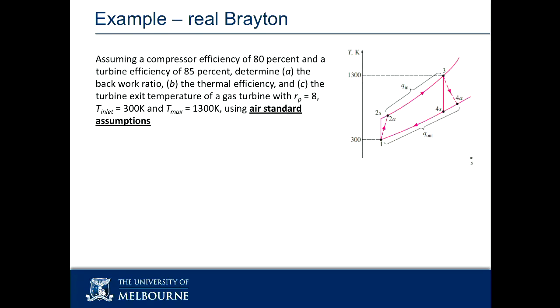What I've drawn up there, let's take our time to look at the graph. We said that we would have an ideal cycle, and our ideal cycles would have the best possible process for any step, which implies that the real cycle has a difference to that. When I introduced compressors and turbines and entropy, I made the point that if I have losses, my compressor and my turbine won't go straight up and down on the TS graph. They will increase in entropy a little bit. So we'll map our way around this guy.